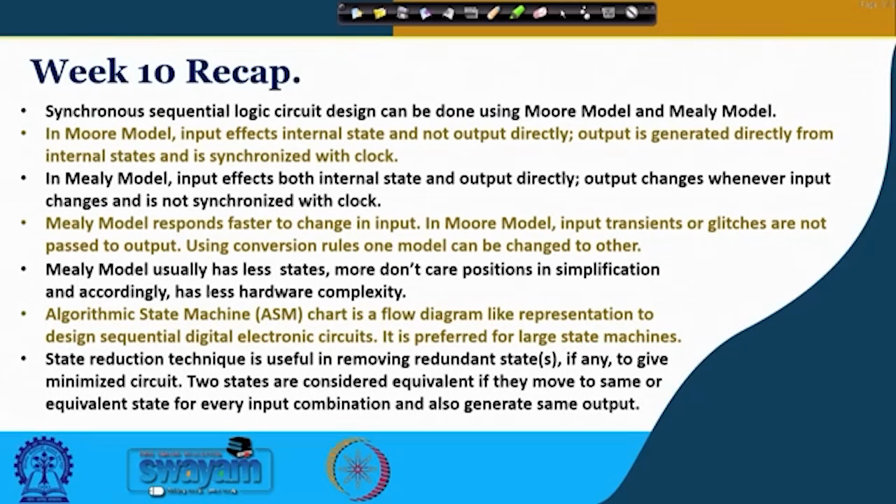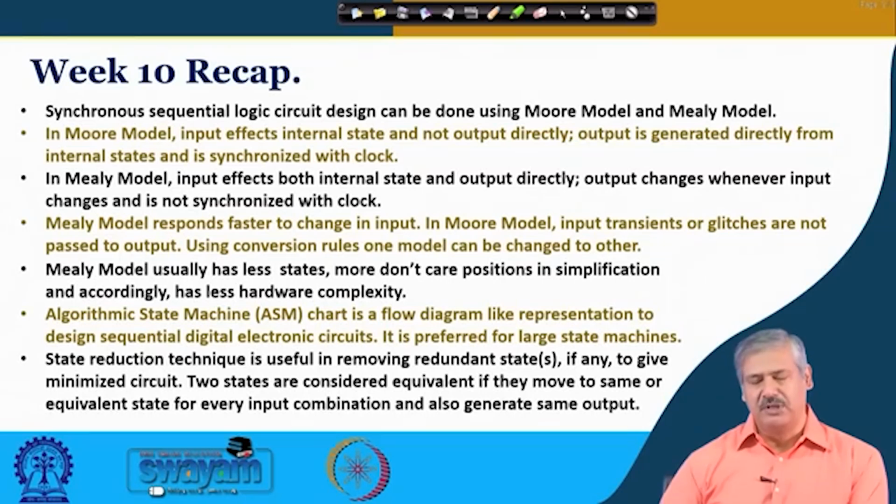Very quickly, what we saw in week 10 is how we use Mealy model and Moore model to design synchronous sequential logic circuits, and we had a comparison of these two different modeling techniques. In Moore model we had seen that input affects the internal state and output is generated from those states only. So, input does not directly go to the output logic generation. In Mealy model the internal states as well as input together act and generate the output of that particular circuit.